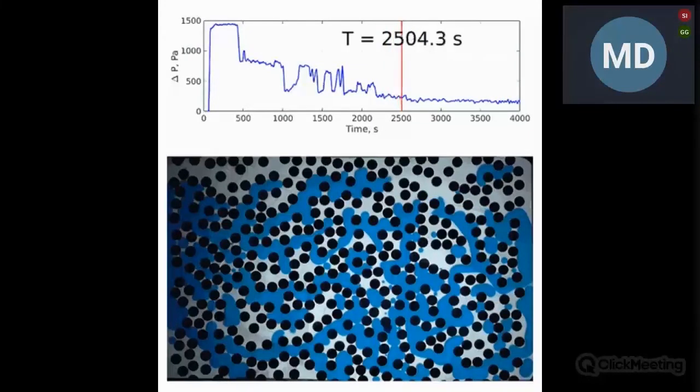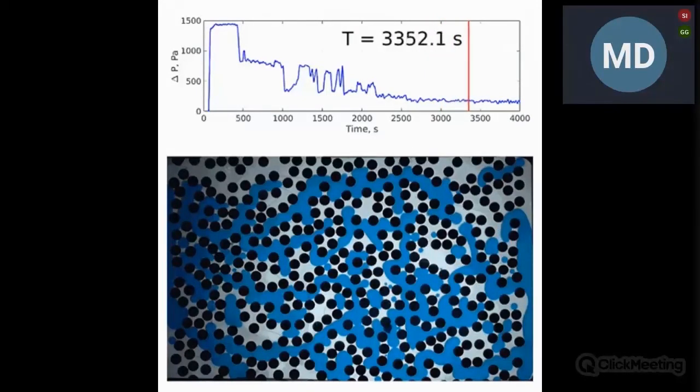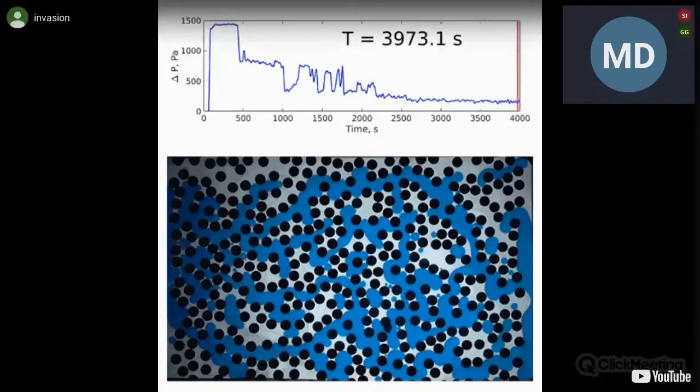In this case, it's water and mineral oil. And the less viscous fluid invades the space occupied by the more viscous fluid. There is a surface tension. And the result of the simulation is the shape of the front and the final saturation. So how much of the invading or defending fluid stays in the domain after the front reaches the steady state.